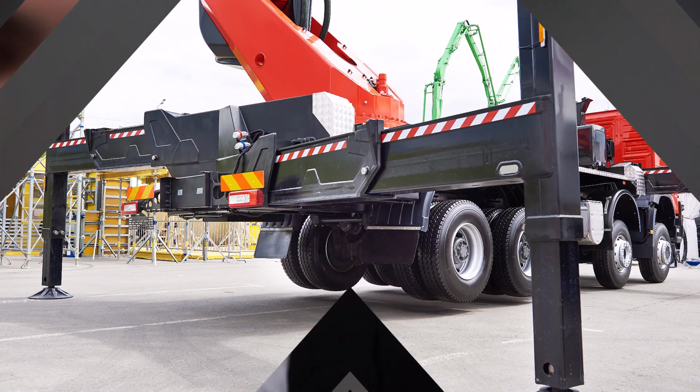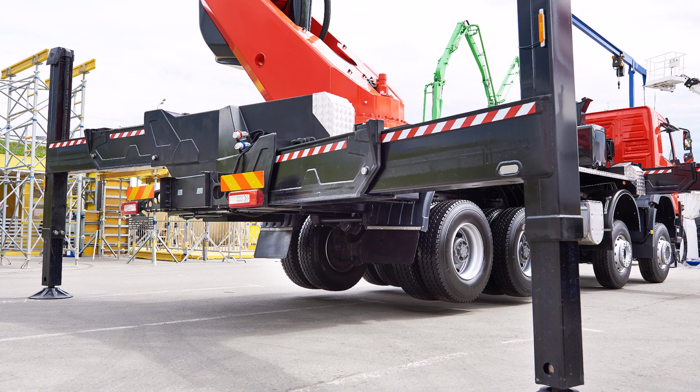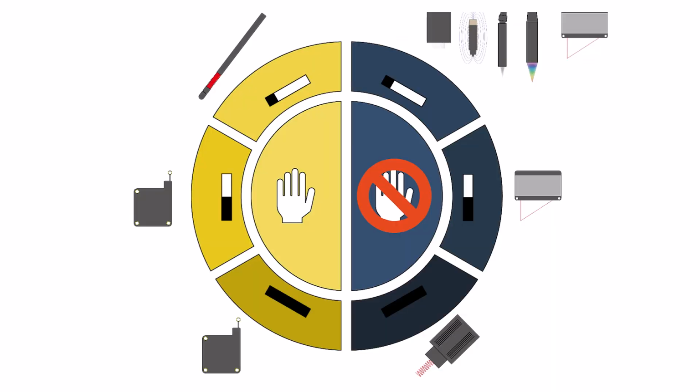Now, to sum all of this up and get a small exercise out of it, we will look at three very different examples. In the first one, let's say we're manufacturing trucks and want to measure the displacement of its outriggers. In this case, our target is not fragile, and to keep everything cost efficient, we therefore go with a contact-based solution. Since the movement is typically more than 500 millimeters, we need a long-range measuring system, and therefore the draw wire sensor would be a good choice here.